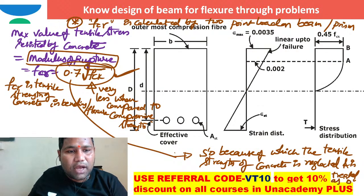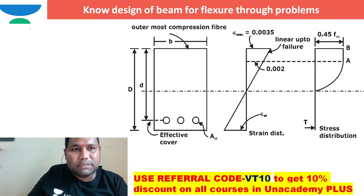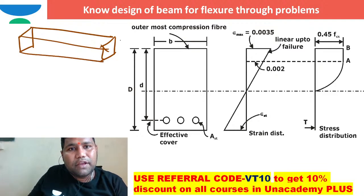Some people will also ask us, sir, how this FCR is worked out in the laboratory. Maybe I will take a specimen of dimension 150 by 150 by 750, and this is the simple support and this is the simple support. Here we apply two transverse loads.